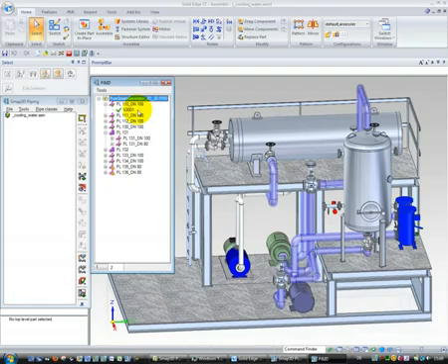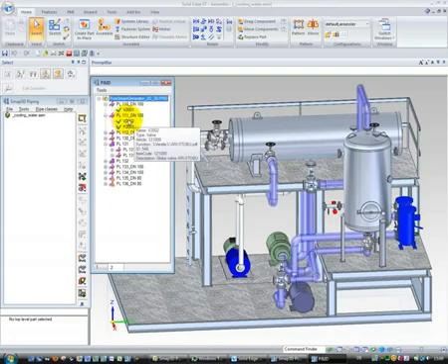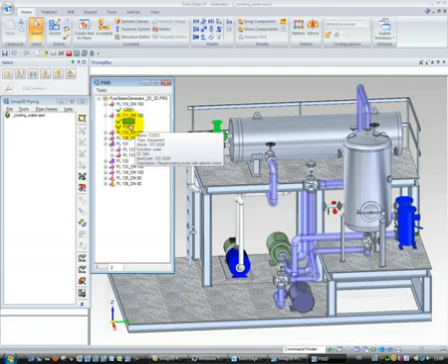Below these entries we see the content of such a pipeline, which is also delivered from the PMID. That means every entry below a pipeline does represent the content which is required and which is defined on PMID level and must also exist in the 3D assembly of the pipeline. In this rectangular field we see all the information delivered from the PMID with this interface into the 3D assembly, which can be used for assigning and linking information from PMID to the 3D content.